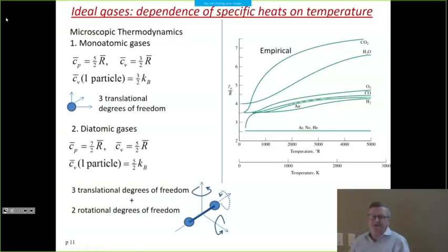Okay, so what is this K? Well, to the rescue comes, again, microscopic thermodynamics or empirical observations. Let me start with empirical observations. Take Cp measurements, renormalize to the ideal gas constant, Cp bar per R bar, and measure it for argon, neon, helium. It's all just right here, 2.5, plus or minus practically nothing.